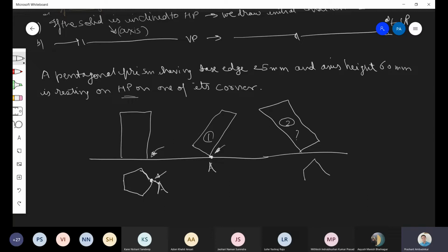It will incline like this. Then what is this? How many points do we have here? Is it a corner now? No sir, it is an edge. So is this correct? No, sir. This will not be correct. So if you incline it in this direction, this will not be correct. In order to incline it in this direction, you will have to draw the pentagon like this. Now this pentagon can be inclined like this, and here we will get a corner.